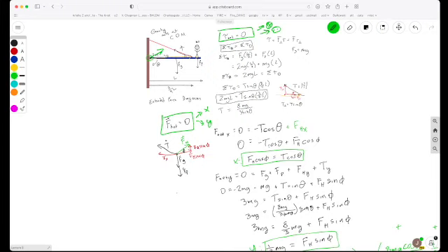Other pieces to remember, again, this is an extended force diagram. That's, as the name suggests, when we just take the forces and draw them where they are acting on an object. So this helps us calculate and visualize torque. And then down here, we have a free body force diagram. And that's when we collapse the object down to a point and draw all the forces acting from that. And that is helpful for visualizing and calculating forces and force balance.